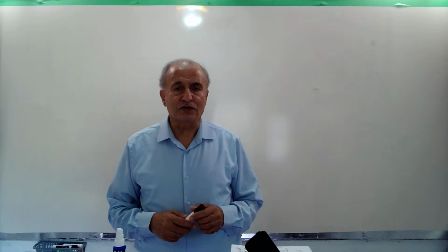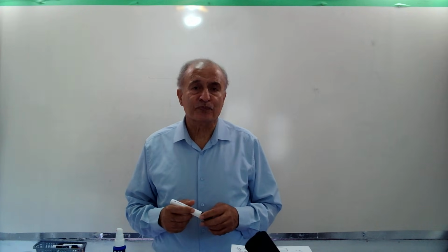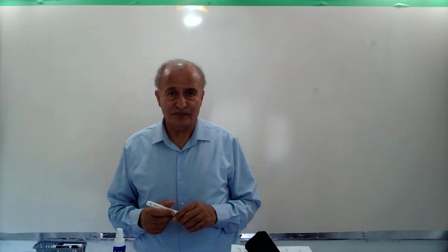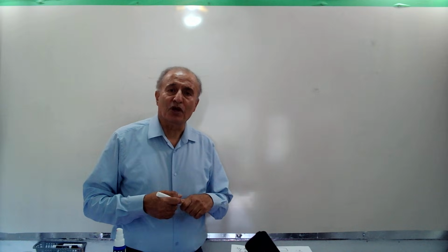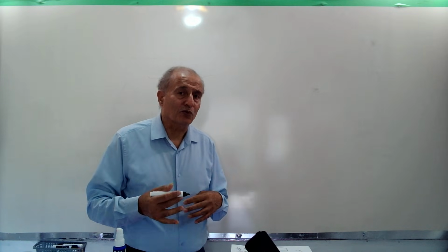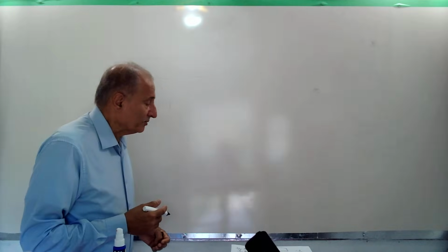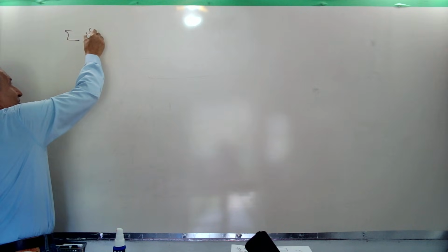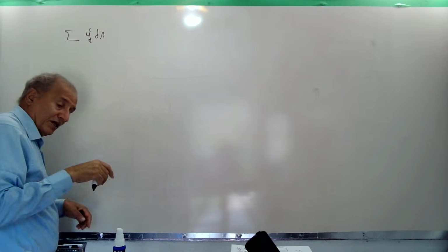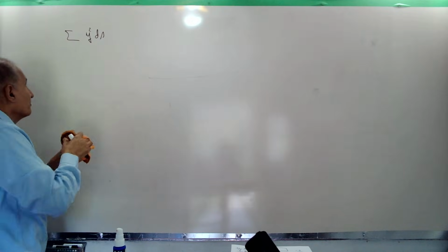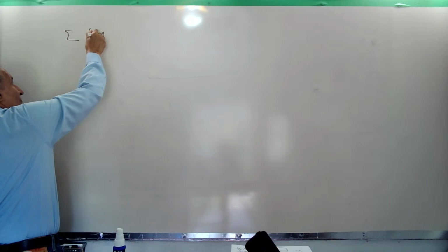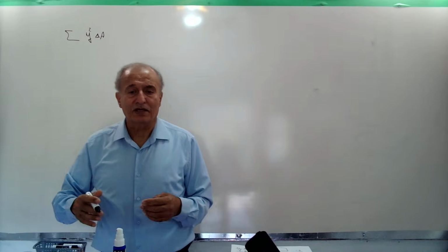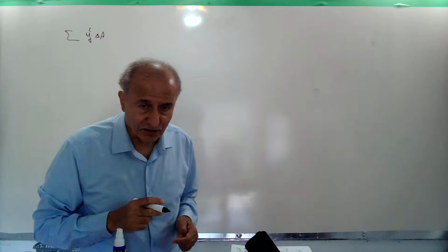I'm Mohsen. Today in this video we want to talk about area moment of inertia I and polar moment of inertia J. In deriving the formula for bending stress in the previous video, we arrived at a mathematical expression, y squared delta A, which is called the second moment of a small tiny area.